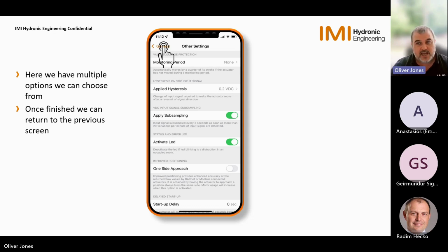Now, obviously, this can create another problem because it won't show errors. But if you've got other versions of the standard actuator, you can force feedback from an error onto the system, onto the BMS, and we can physically get an alarm on the BMS to say that there is an error, that the input line is broke, or there's no 24-volt power to that actuator anymore.